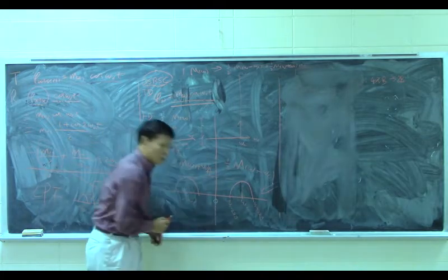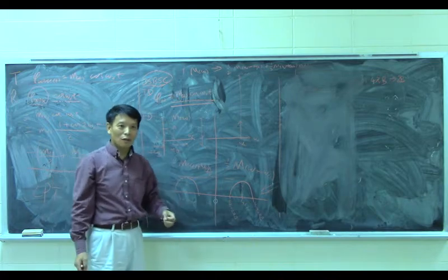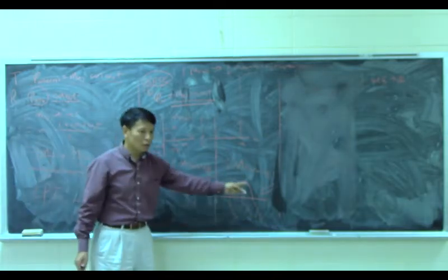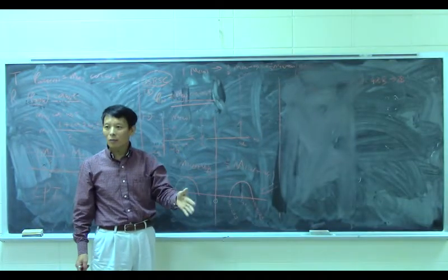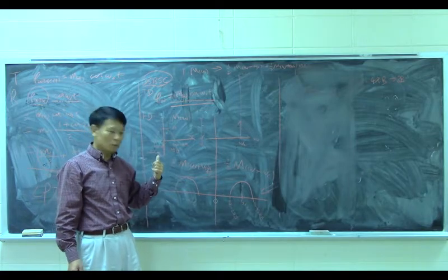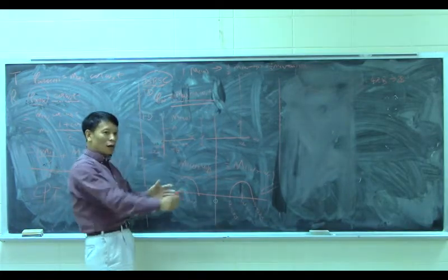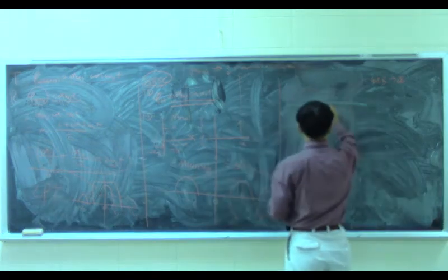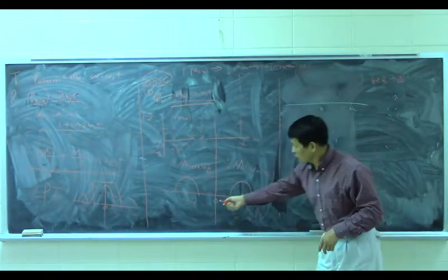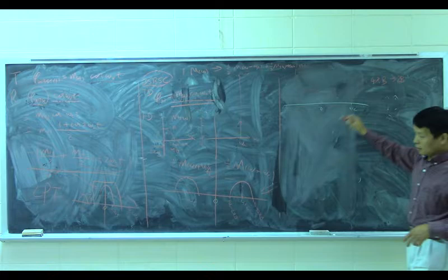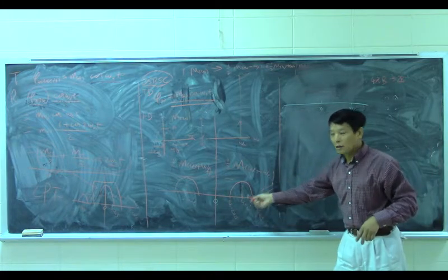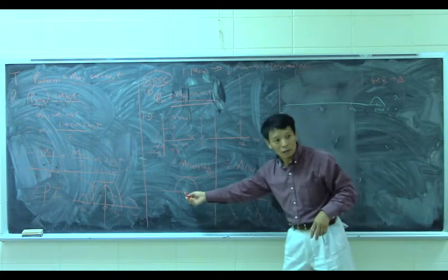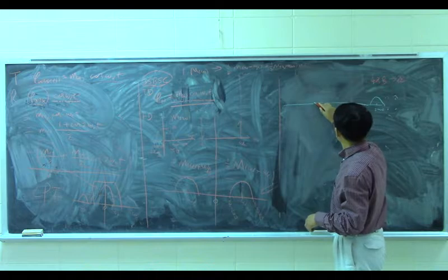0. It's here, right? Because the two are symmetric, so the center is 0. Now, this modulation process shifts this spectrum to be centered at omega c and negative omega c. So what we do is we shift this total thing to the right, move this 0 to omega c. This is 0, this is omega c. So we shift this 0 to here. Then where is this? This one will be 2 omega c, right? Where is this? 0, right? It will be like here.